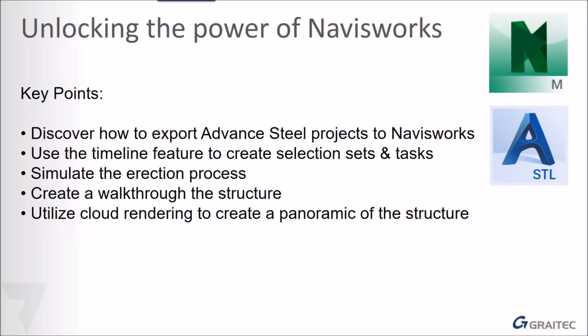I'm not going to go through Navisworks in total. It's such a vast and big program, so I'm just going to go through some key points. First of all, we're going to look at how we can take the Advanced Steel project out and get it into Navisworks, and then we're going to use a feature called the Timeliner to timeline the project and simulate the build and erection sequence of the project.